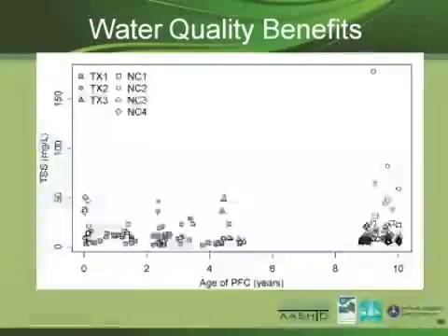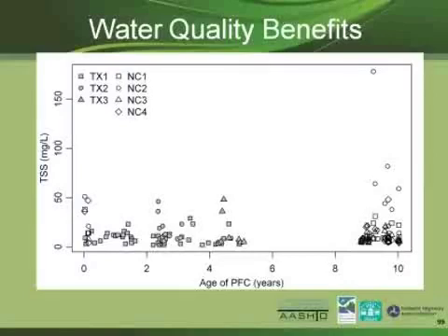And the North Carolina DOT considered 10 years to be the effective structural life of the pavement. So in the middle of Bill's study, they went out and milled them and replaced the pavement. Here's additional monitoring from Bill with brand new pavement. What this says is that under the right conditions, and remember Bill's was on an interstate, similar to some of our sites, the water quality benefits last for as long as the pavement lasts. And the amazing thing is that no one is doing any maintenance at all. There's no street sweeping, there's no flushing of the pavement, there's no nothing. This is install the pavement and walk away.